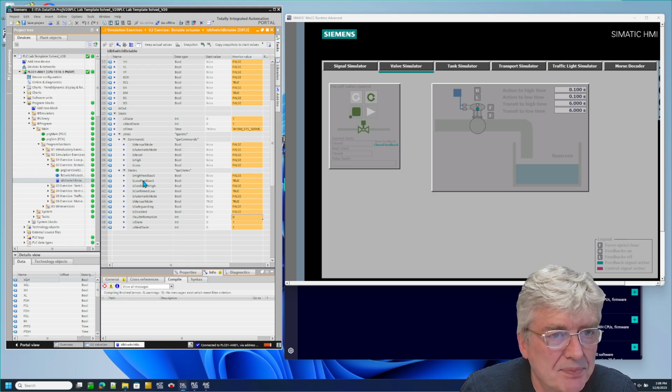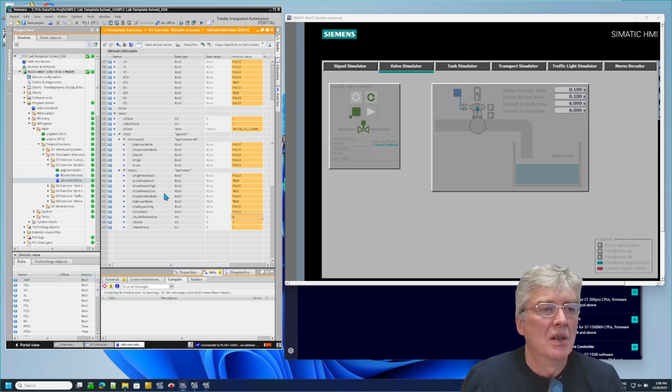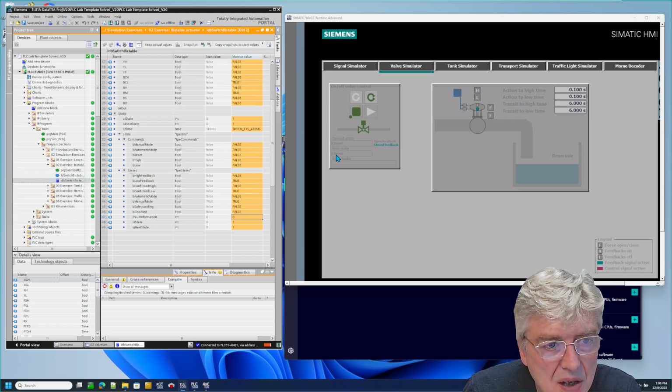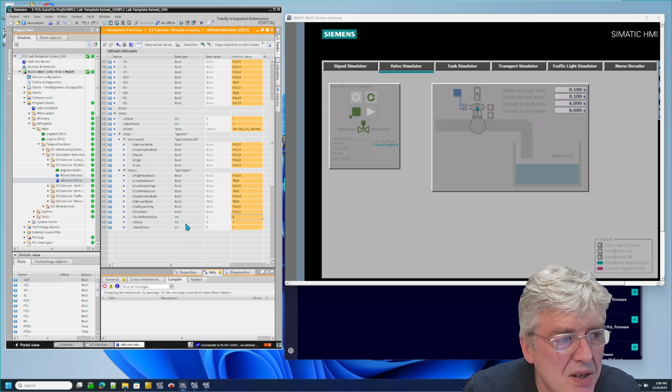Low feedback is here. That's the one that's true, so it's closed. And the high feedback, then it's open. High is open and low is closed for a valve. For a motor, high would be running and low would be stopped. And here was the next state, which is this one. Where do you want to go next?